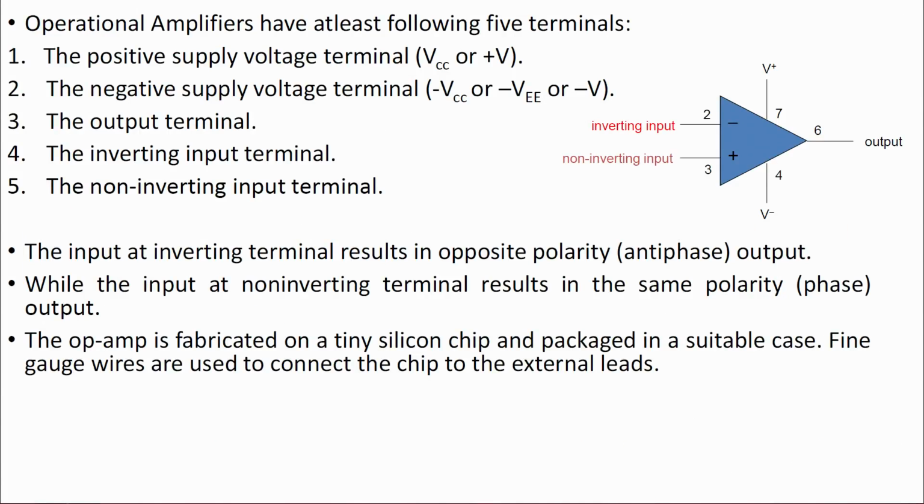And when we talk about an op amp, generally we will see 5 terminals. Actually an op amp is an 8 terminal device, but most of the time we talk about 5 main terminals: positive and negative supply voltage, output terminal, and inverting and non-inverting terminals. Pins 1 and 5, which you cannot see here, are used for offset, while pin 8 is not connected.